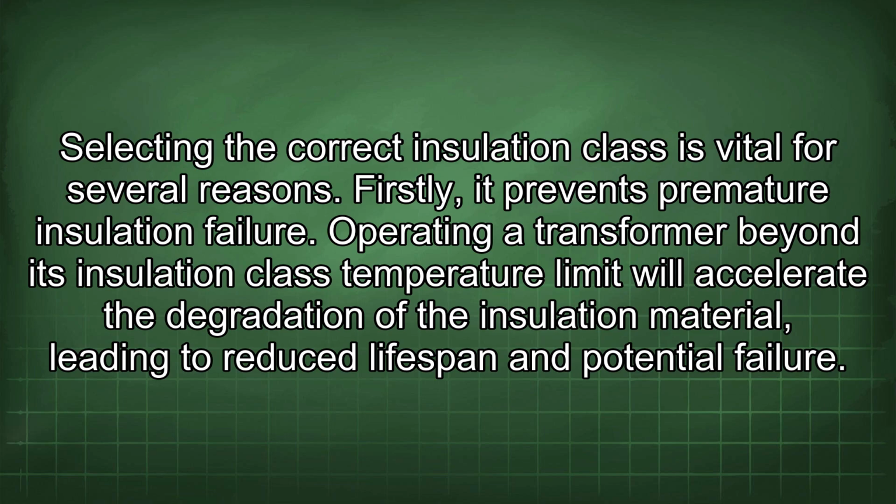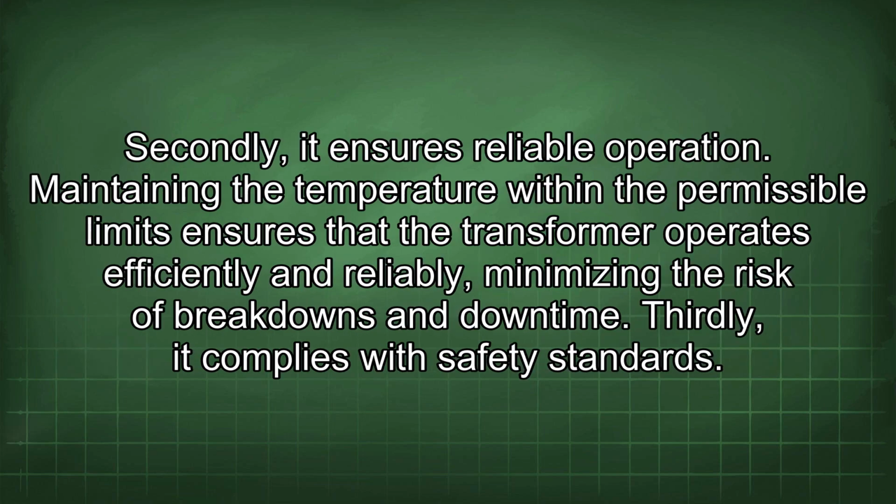Selecting the correct insulation class is vital for several reasons. Firstly, it prevents premature insulation failure. Operating a transformer beyond its insulation class temperature limit will accelerate the degradation of the insulation material, leading to reduced lifespan and potential failure. Secondly, it ensures reliable operation. Maintaining the temperature within the permissible limits ensures that the transformer operates efficiently and reliably, minimizing the risk of breakdowns and downtime.